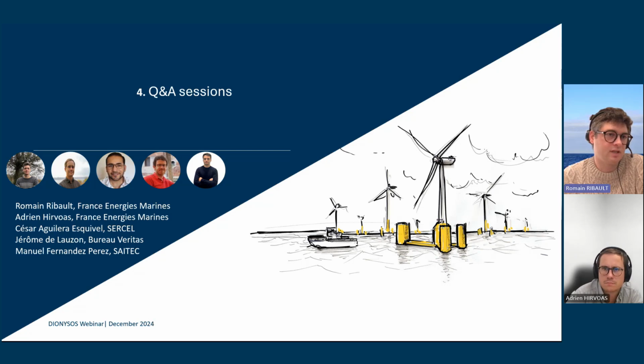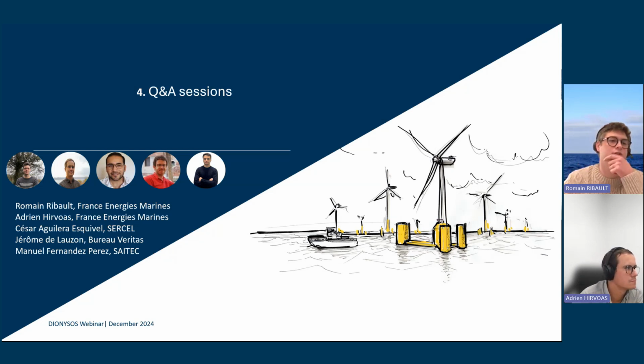Adrien, did you manage to validate the acceleration spectrum prediction with in situ data, with a buoy plus measured accelerations? Yeah, so our deep learning approach for the prediction of acceleration was based on synthetic data. So the first step was to validate the prediction based on the numerical model output from OpenFast. And then we tried to validate the prediction also with the data measured thanks to the acceleration.